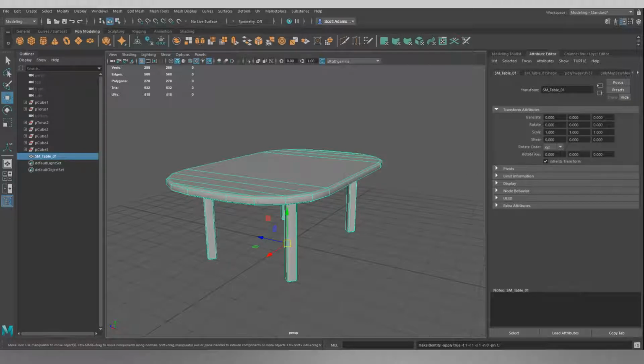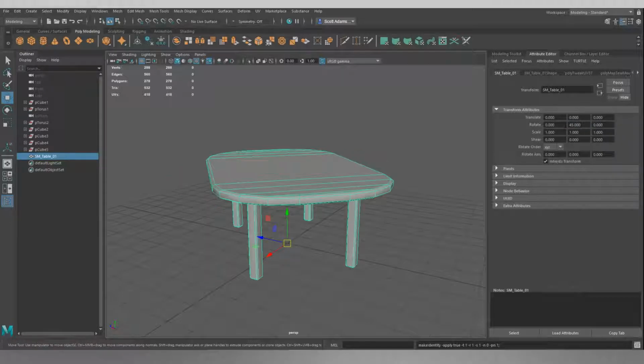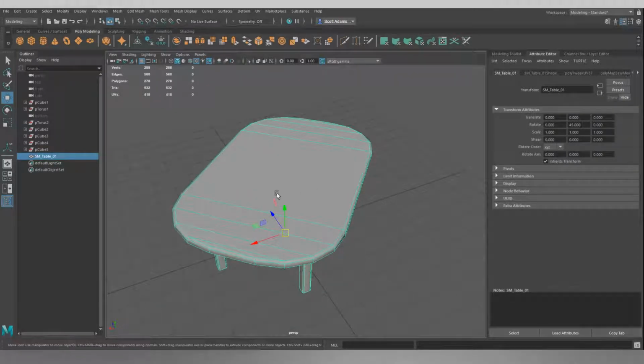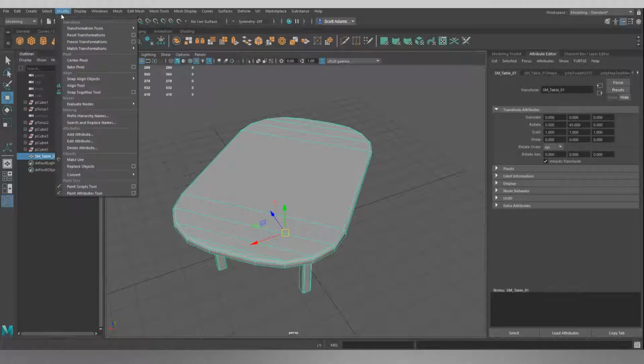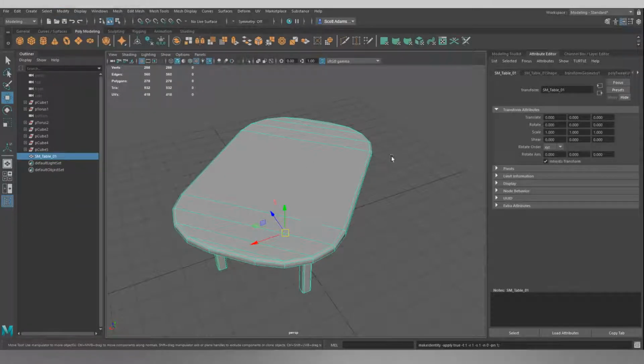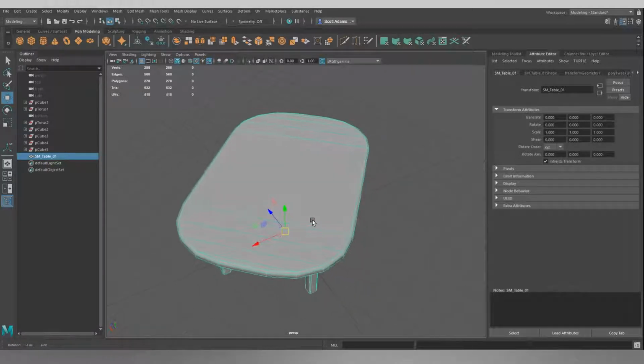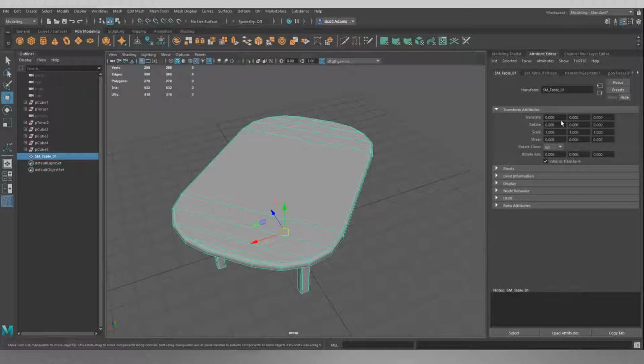Now what this does is, if I apply a 45-degree Y rotation, this value is going to be carried through. So every time this is placed in engine, the engine is going to place the model, then it's going to rotate it 45 degrees to the Y. If we freeze transformations, it makes this the new 0 value for the model, which cuts out processing power being used on all those little calculations as we go.